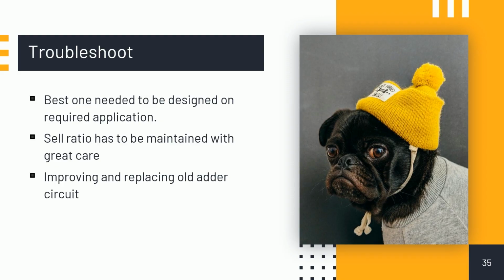The best one can be chosen based on the required application. For example, if we consider area as the main factor, then designers can prefer the 8T full adder design, which has lesser area. And similarly, if we consider power consumption as the main factor, then designers can prefer the 14T full adder design, which has lesser power consumption.